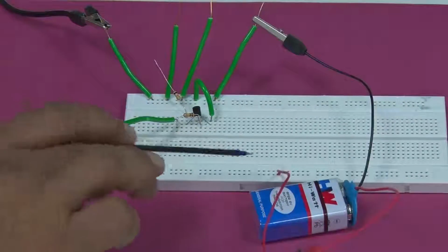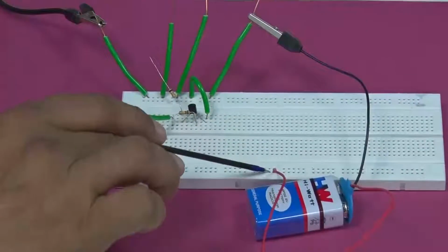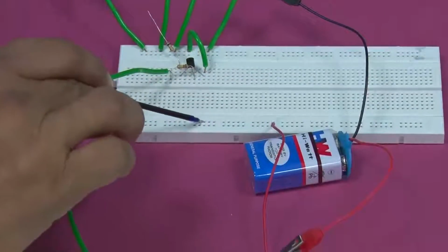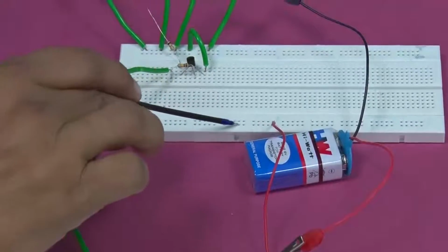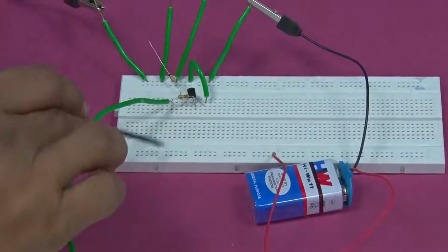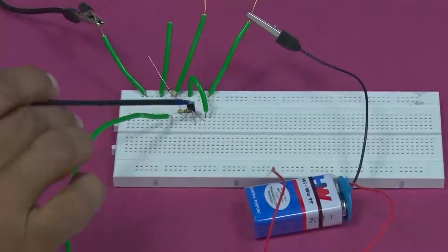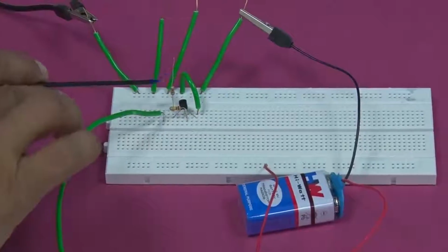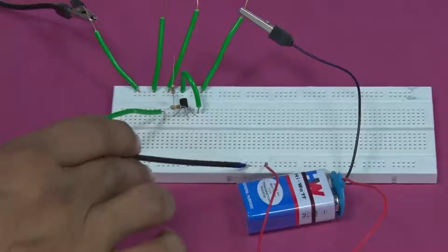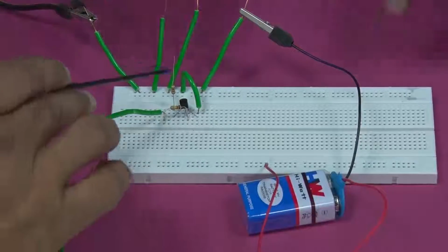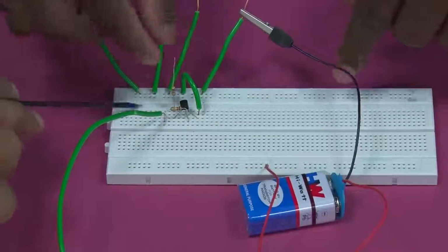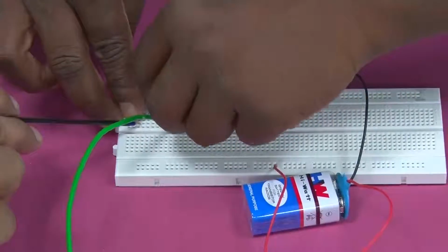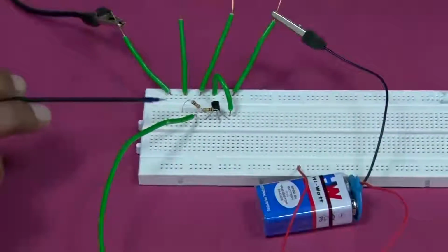Good. So, this is our 9 volt line. So, this whole line here becomes 9 volt. Okay. All these holes are at 9 volts. Fine. So, the collector has to be connected to the resistance that you have done, and the other part of the resistance should get connected to this line somewhere. So, you can join it anywhere you like, you can join it here. And then from here,